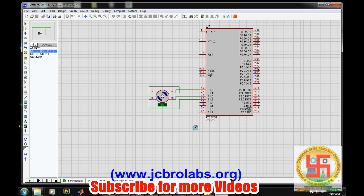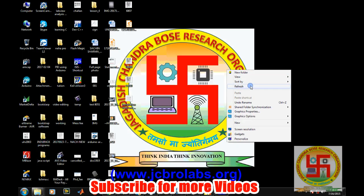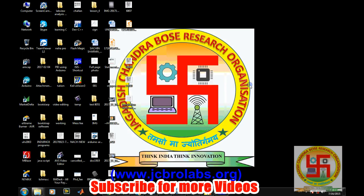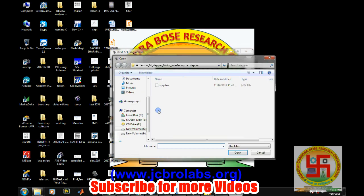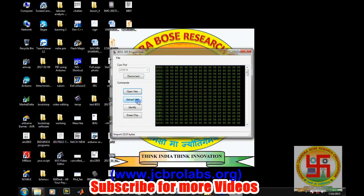Now you can see it's rotating, so it is taking some steps and then it is making a complete revolution. So similarly you can also do it on the previous one. That means our code is working, and now let's burn the program on the hardware. So let's open the programmer, connect, then erase chip, then open hex, select the hex file and simply upload it.